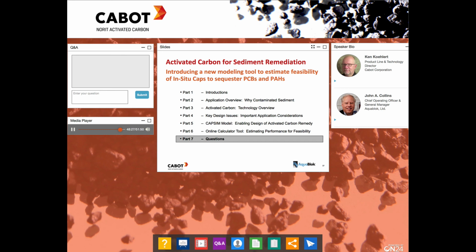John, maybe you have an example of a PAC versus GAC system? No, it's an excellent question, but all of the pilot demonstrations that we've been involved with have been comparisons of, say, AquaGate plus PAC versus Sedimite. Both of those products are powder-based products. I have not seen a side-by-side comparison of a PAC-based sand active cap versus a granular activated cap layer.